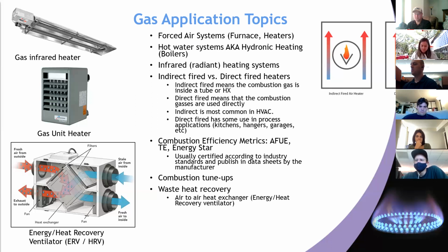The IIAC does have a little handheld flue gas analyzer. We just put new batteries in it, so it should be working. And what it will do is test the composition of the gases coming out of the flue of a furnace or a boiler or something similar. And it will show what the excess oxygen level is coming out.